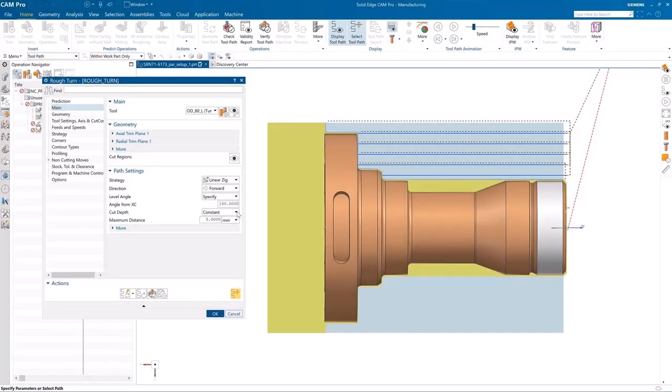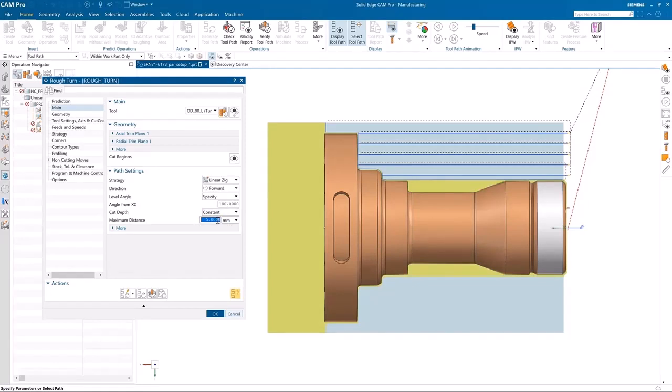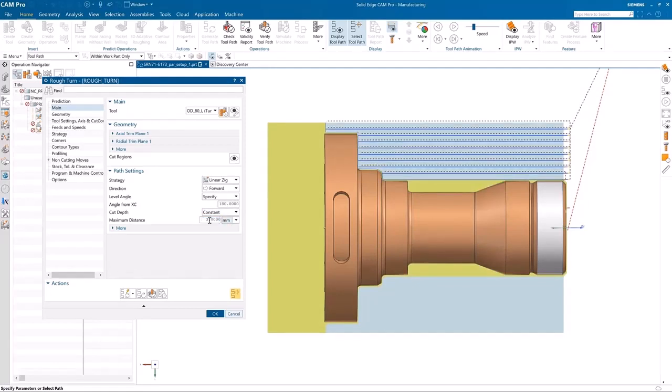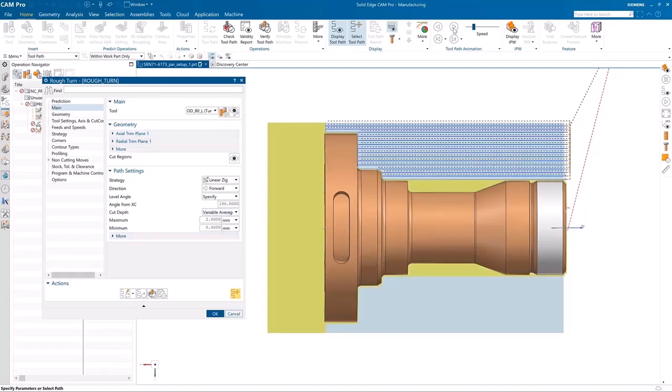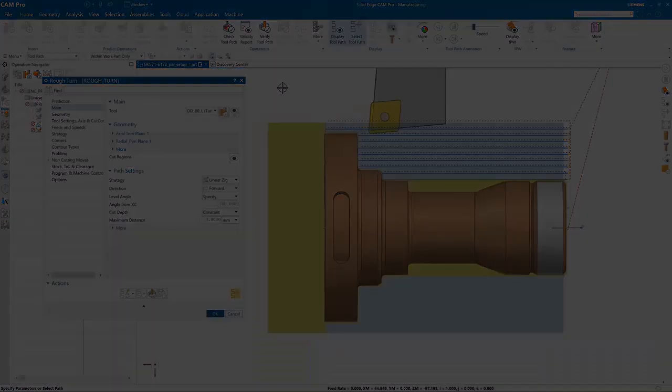With auto-generate for simple turning operations and certain 2.5-axis operations, you no longer have to generate the operation. As soon as enough parameters are available to calculate the toolpath, Solid Edge CAM Pro takes care of it. This makes NC programming faster, allowing you to review the results quicker. Similarly, any changes that require recomputation are automatically performed. See the latest results as soon as the parameters are changed.